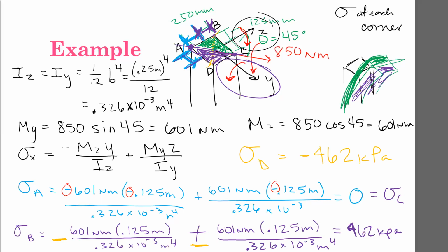So the neutral surface is a plane that passes all the way through longitudinally through the member. When we're looking just at the cross section, we just see one edge of that neutral surface. Does that make sense? So this is a rectangular plane that cuts across the diagonal and then all the way down through the column. That's the neutral plane. Yeah, the axis is just the edge of that that goes from corner to corner.